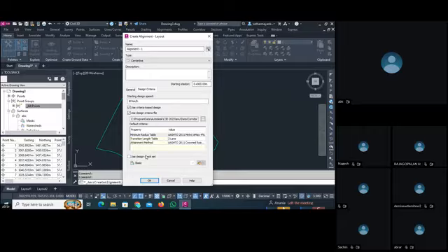It does not design anything, but it only gives warnings like your curve radius is too small, sight distance is not safe, your grade is too steep. So if you manually draw a curve and you set the design check, and this curve does not meet minimum radius, it will give you a pop-up like that.